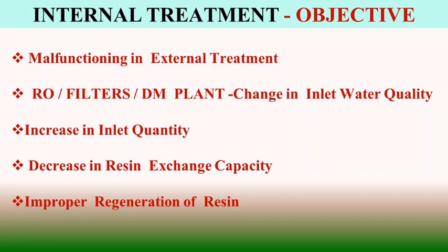So to make it non-adherent to any boiler surface, and to provide anti-foam protection to allow a reasonable concentration of dissolved and suspended solids in the boiler water without foam carryover. And likewise, the purpose is to eliminate oxygen from the water and provide enough alkalinity to prevent boiler corrosion.